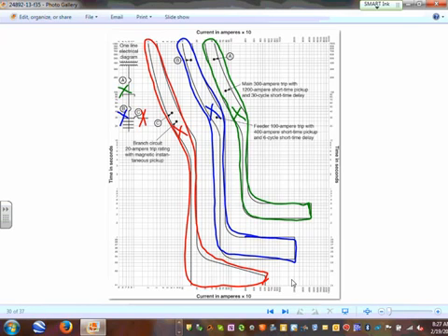How do you do that? You grab a screwdriver and you start adjusting these settings here. Up, tweak, up, down. Here's pickup. You have long time pickup, long time delay, short time, instantaneous. And you can adjust these with the screwdriver. But which number are you going to put it at? These curves, guys, will give you numbers. When we run them in SKM, it will tell you to put this dial at this number, and this dial at this number, to get you a fully coordinated system.